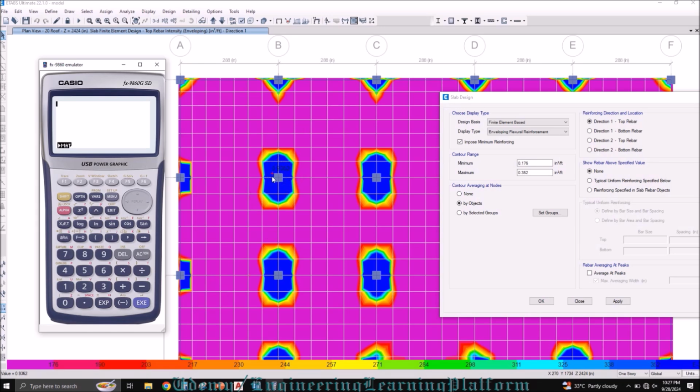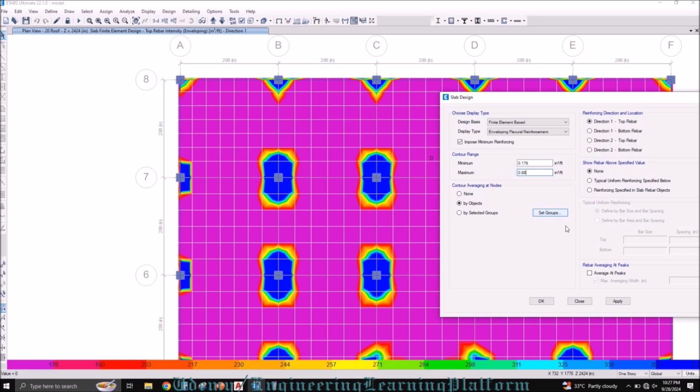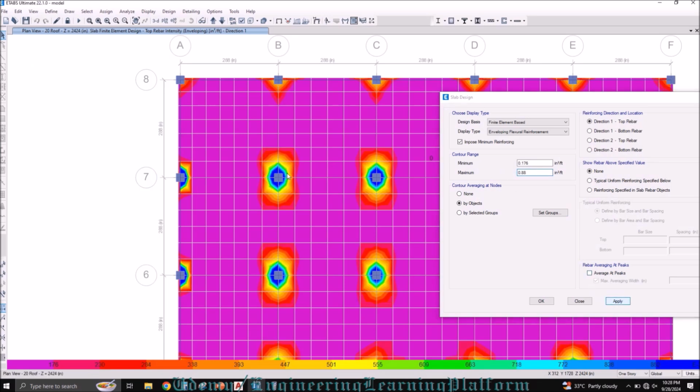You can hover the cursor on the contour and look at the bottom left. The bottom left is showing that this area would be working within 0.8 and 0.89 inch square. So if I add 0.88, okay, 0.88 is still less, so let's add 0.95. We'll check this number in a moment. If this dark blue color vanishes, it means that my extra reinforcement would be sufficient.